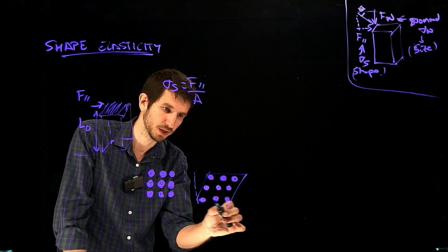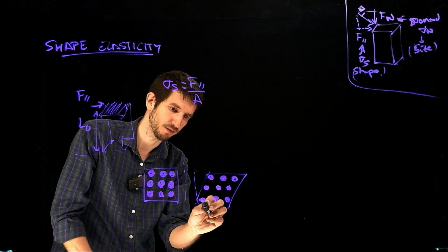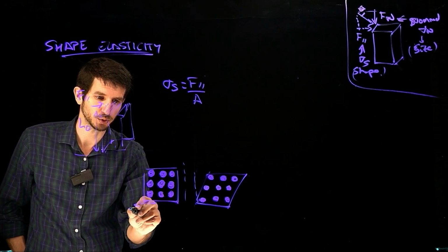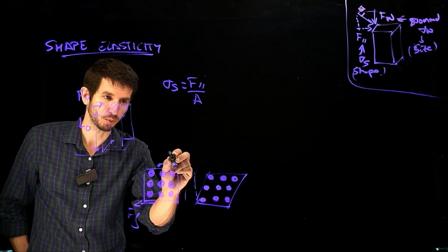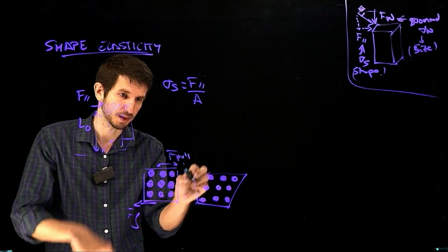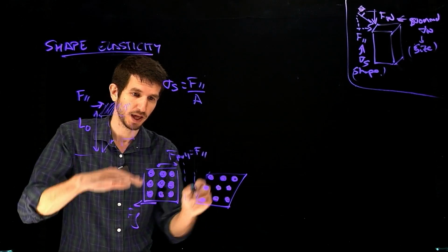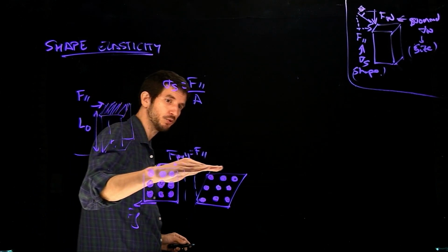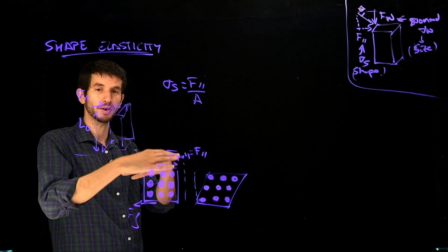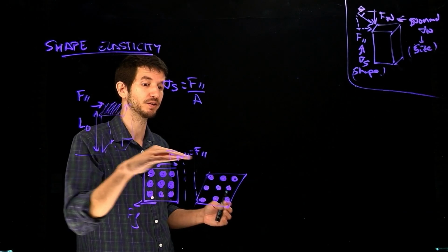And so you see what's happening in here? You had this, and now you have that. Because over here we're going to have a friction force that's acting opposite to the motion, and here I have a pull force. This is a cross section, of course, and I have the pull force that I am applying in parallel. That's the parallel force. And because of that, this layer experiences the forces, tries to move. This one is being pulled by that one moving, but it's also pulled by this one to remain in position. And so I'm going to have a deformation of the shape.